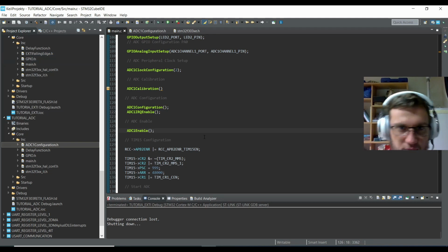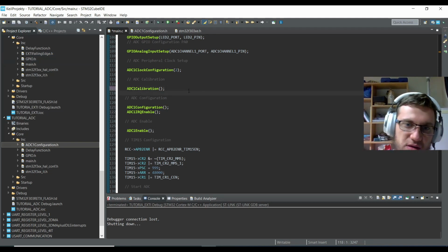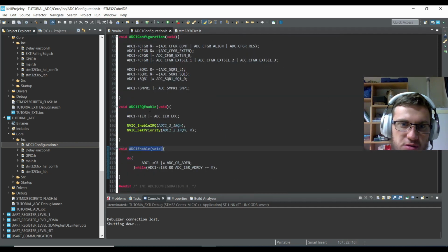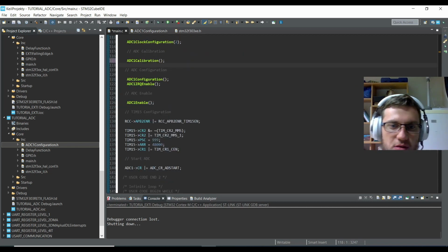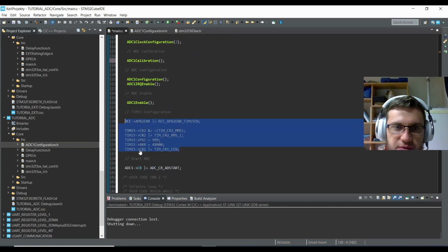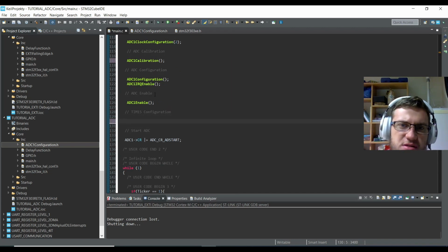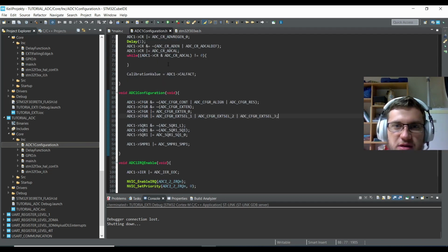And this library is set so that in the configuration we have chosen the timer 15 as a primary trigger source for the ADC interrupt to occur, to start the conversion. So we can also cut and paste the timer 15 configuration. Again, if I do any projects, I 90% of the time use this timer 15 because, as I said, it's not some sort of special function timer. I use it just as a ticker.